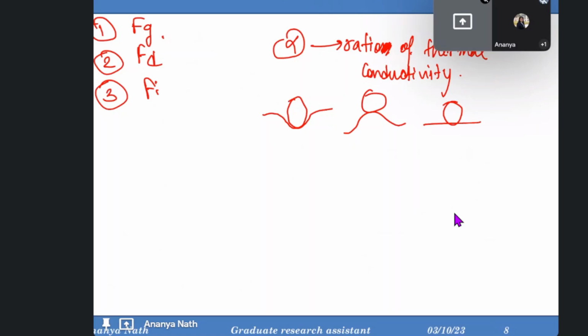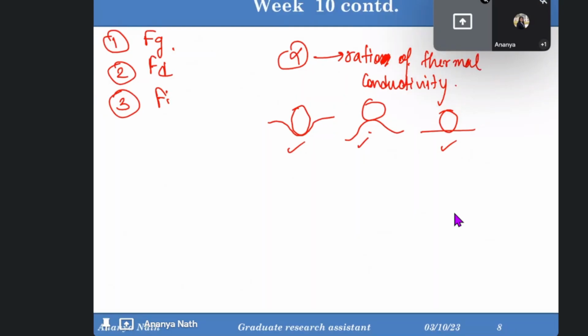If it's like this, it's okay to have it, but it's not always good, because there will be a chance of pushing the particles towards one direction and clustering or agglomeration of the particles at a particular point, which is obviously not desired, because we want a well distributed particle arrangement in the matrix.